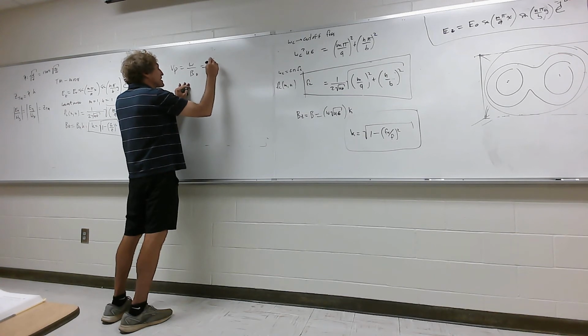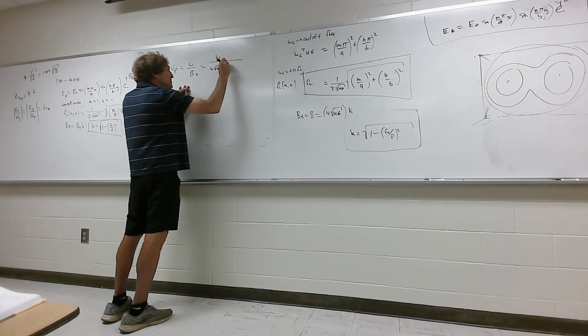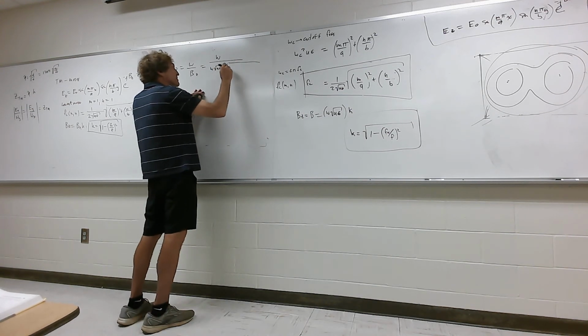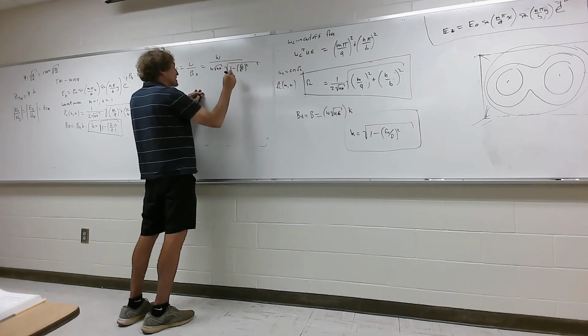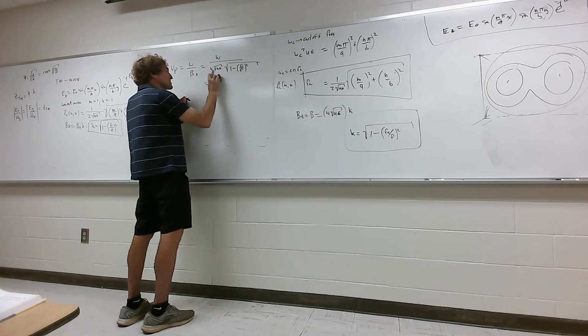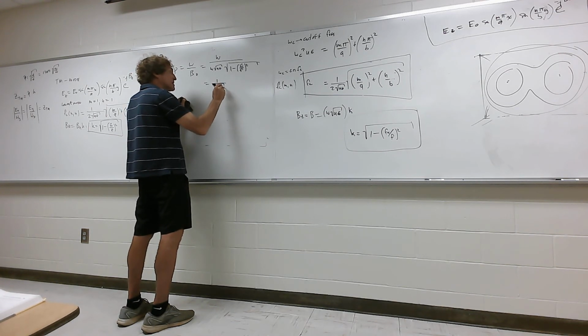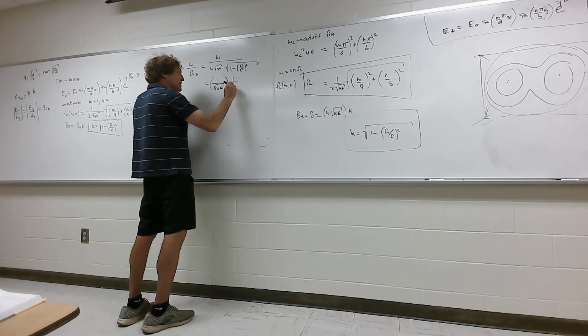So this is going to be equal to omega over beta unguided first, so it would be omega times square root of mu epsilon times the square root of, and I'll just put in k here, 1 minus fc over f squared. Now, one thing you see is the omegas cancel. I get 1 over the square root of mu epsilon, and it's divided by k, right? Now I'm putting that k in here.